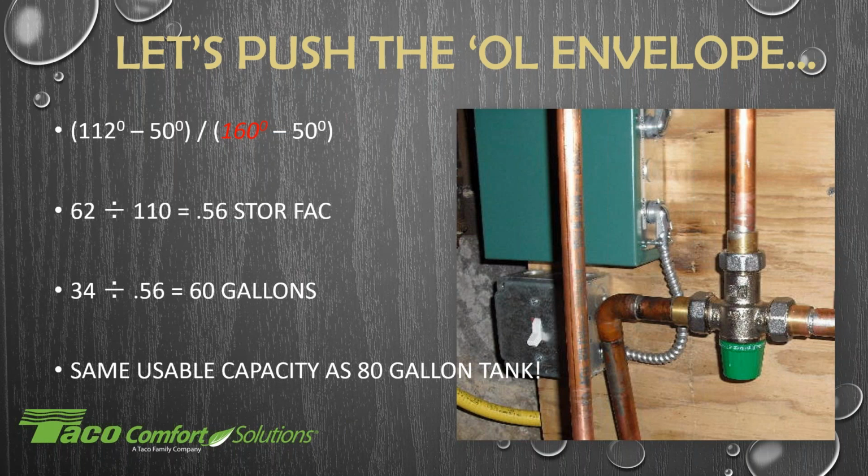All right. So that's your cold water that is supplying the water heater; it will have a T in it and feed into this mixing valve. So if the water heater was 160 degrees and the water coming from the street is 50 degrees, the two will blend to get you that 112 going out to the house itself. So that's what you see here.